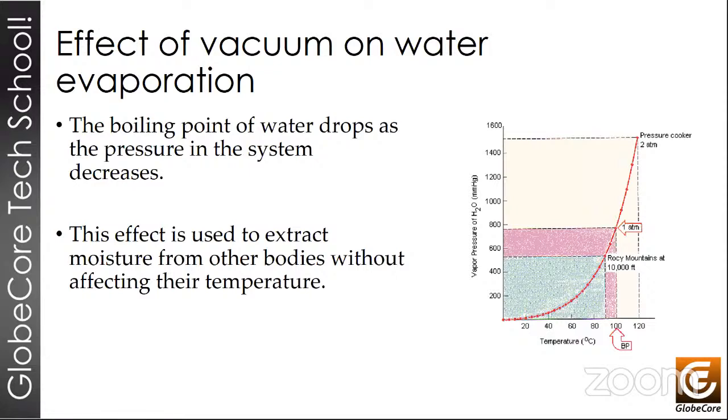And as we can see, it's just a physical process, no chemistry at all, no absorbance or anything like that. So it's a very straightforward and relatively simple process. However, it's important to make sure that oil remains under vacuum as long as possible to extend the degassing and drying, and of course to increase the surface area of the oil as much as possible. There are various methods of doing this, but you want to achieve as high contact with the oil as possible, and this is done by spreading it very thin, like in a film.